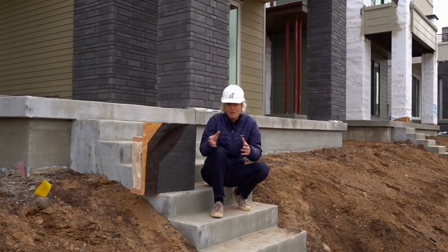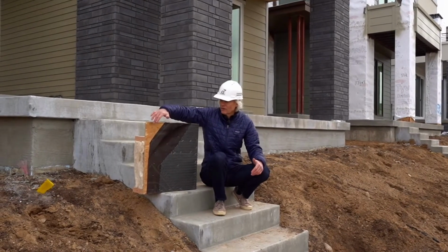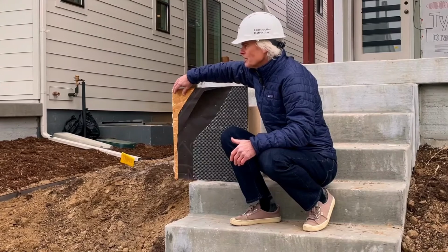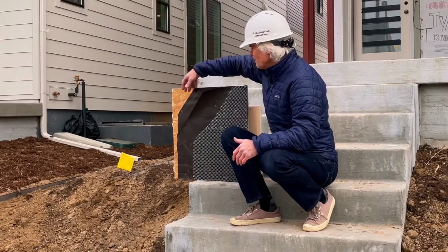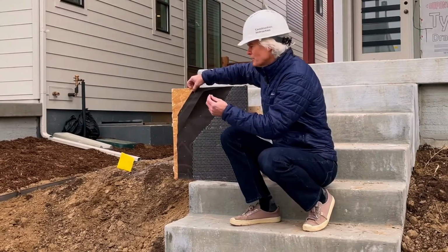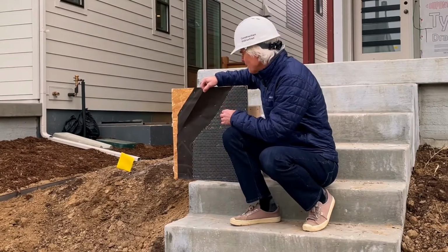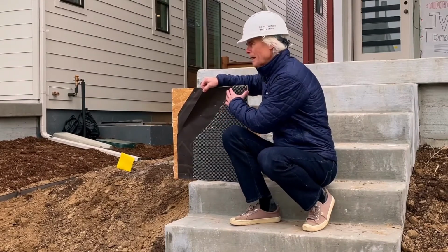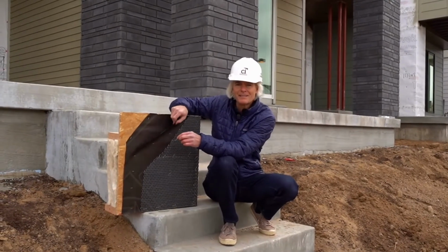And that typical masonry cladding that we see is really constructed over an OSB sheathed material with typically 2 layers of grade D paper. Sometimes we'll see out on this site that there's a layer of some weather resistive barrier, then an intervening layer of grade D paper over the top with expanded metal lath. And really what we're trying to do with this second layer is this is a debonding layer.